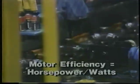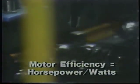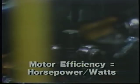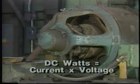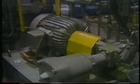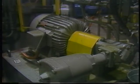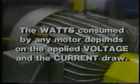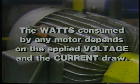Now, as we said at the beginning, a motor is a converter of electrical energy into mechanical energy. Its efficiency is a measure of how well it does this. Efficiency equals the mechanical output in horsepower divided by the electrical input in watts. Watts of DC power equals current times voltage. When the power is AC, the relationship is a little more complicated, but the watts consumed by a motor always depend directly on the voltage applied to it and the current it draws from the line.